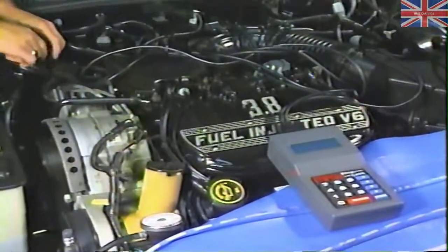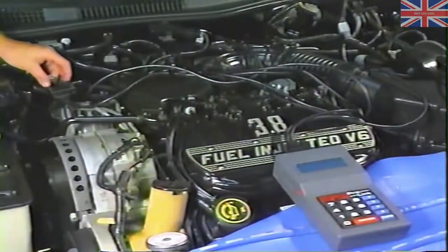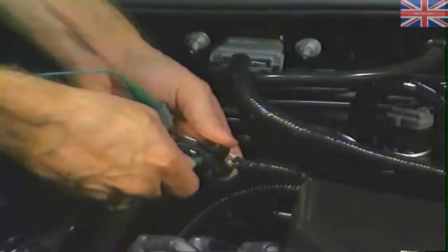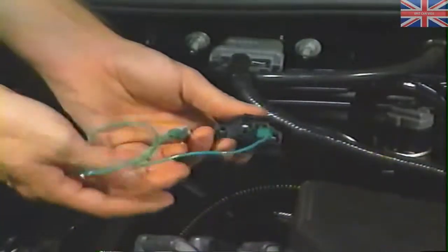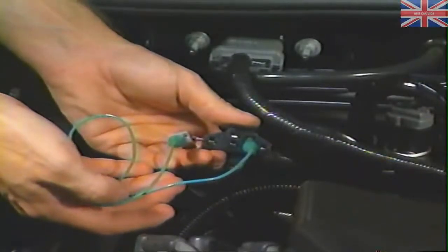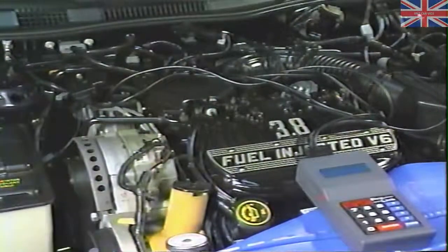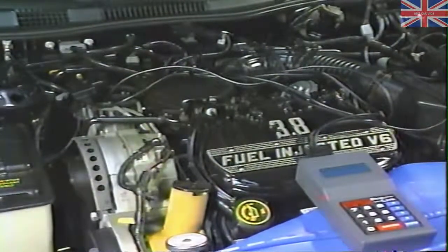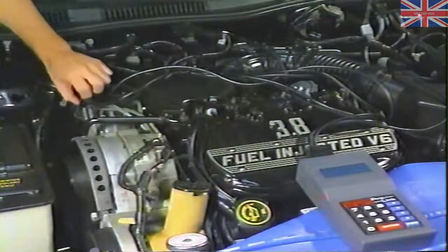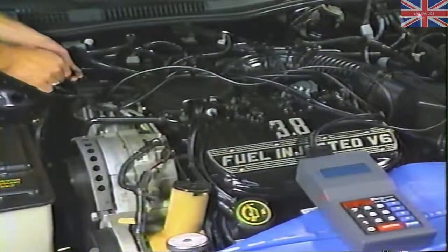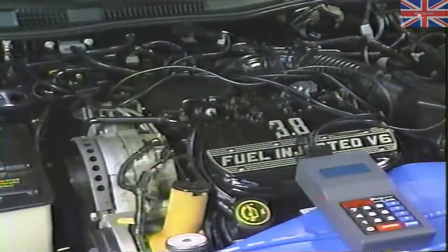The first step in doing an engine running self-test is to deactivate self-test. Disconnect the jumper wire from the self-test input terminal or the individual lead from the scan tool connector. Turn the engine off. Wait 10 or 15 seconds and restart the engine. Reactivate self-test by installing the jumper wire or plugging the individual lead into the scan tool plug.